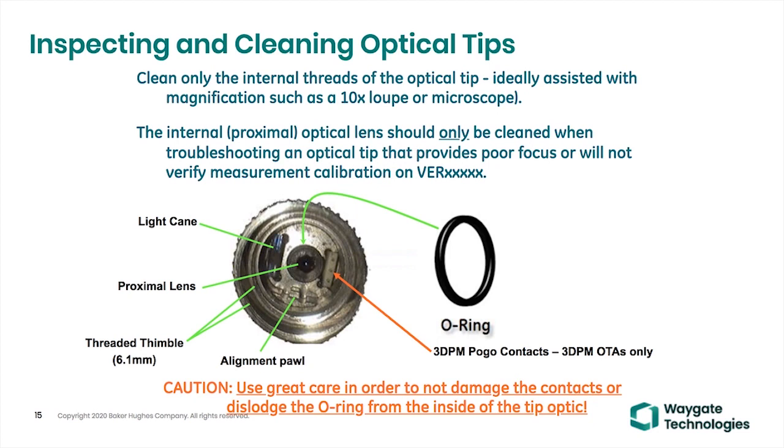If you follow that best practice and your measuring accuracy is within the tolerances of that block, there is no need to do any periodic maintenance. If there's a calibration requirement, that would typically be if you're buying a new tip, new probe, or having some repair done. Paul, anything to add to that? Tom, I think that's pretty clear and thorough.